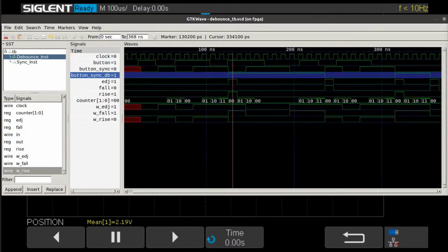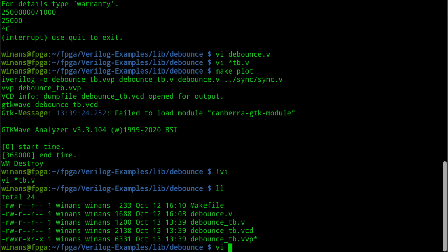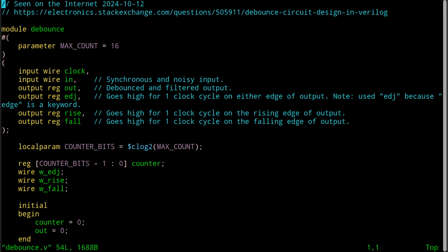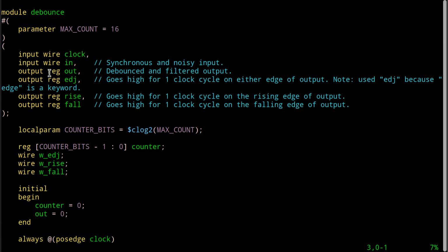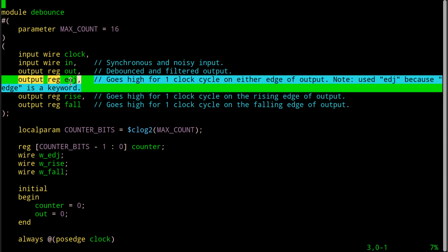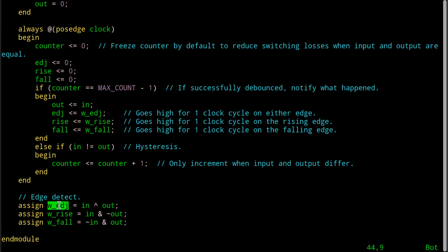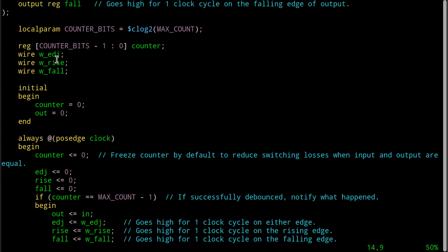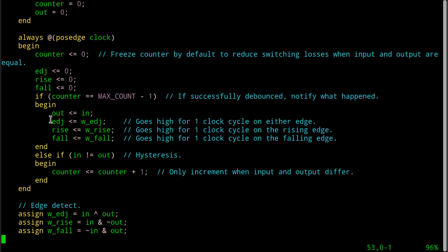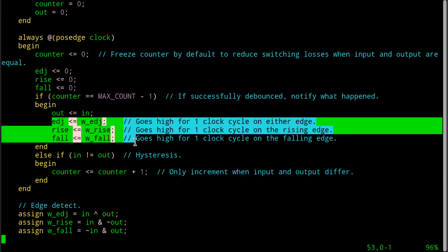Leave it in there. What happens is, if you have a thing like this and you want to create a general purpose library module out of it, and it's got extra outputs on here, if you don't use these outputs, the synthesis tool, the compiler, will detect the fact that that goes nowhere and is used for nothing. Therefore, when it's building the circuitry down here that generates it over here, what does it do? It generates it there. Yes. And then it propagates it over here with latches and wires and gates and all these lots.